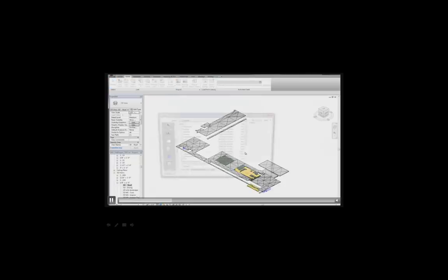Okay, so once you do that, then you can insert the schedule from that template that you created, right? When you do that, that'll bring in the schedule, and the schedule is going to automatically populate with all the roof elements in your project, along with the areas of each. Whether or not the roof is steep, and the SRI columns, are going to populate based on the inputs that you put in.